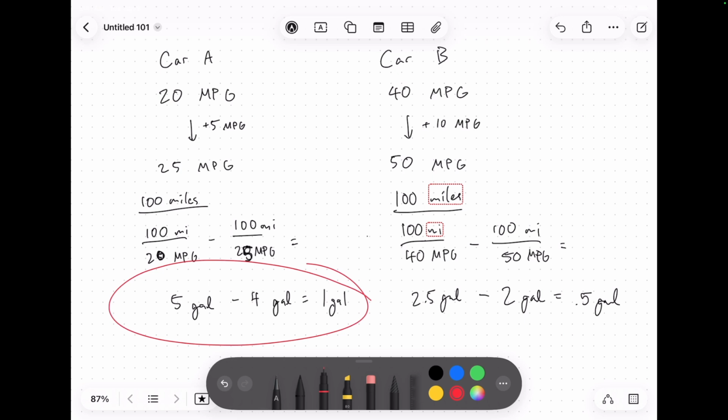And that's because when we're looking at the consumption of fuel, you're actually looking at the inverse ratio. The whole idea is MPG is a very poor metric for describing the relative amounts of consumption over set distances. It's actually a 1 over X. And the main takeaway here is that improving the fuel efficiency of really inefficient, dirty, big vehicles is going to save a lot more fuel and energy than upgrading vehicles that are already pretty fuel efficient, right?